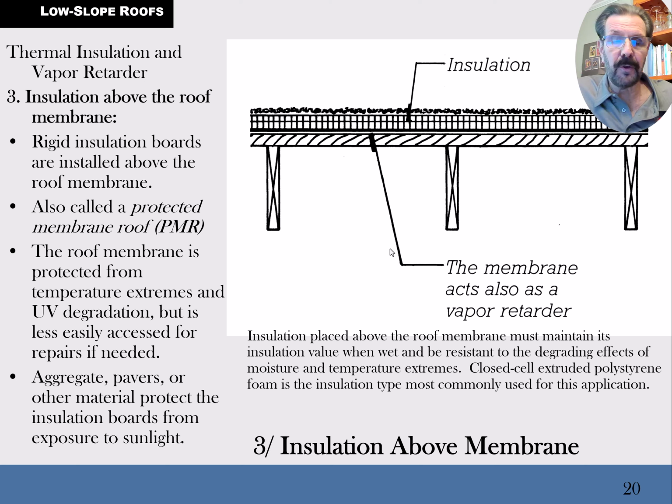And then they put the gravel on top of the insulation to keep it from blowing away and keep it from deteriorating in the sun. So either way, the gravel is there to protect it from the ultraviolet rays of the sun, and it's ballast. Ballast means that it's weighing it down. In truth, when we have shingles, the asphalt fiberglass shingles that we use on most of our houses, they have a sandy material on them, and that's called ballast also.